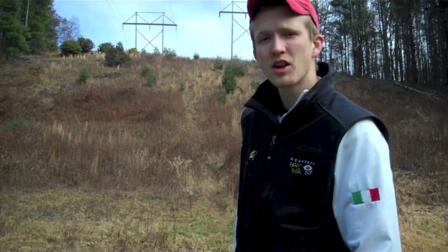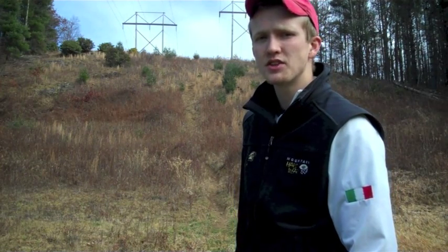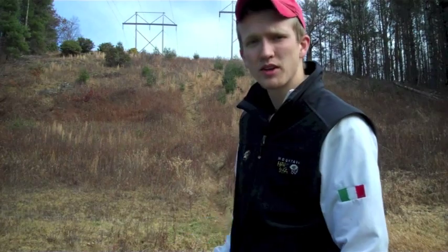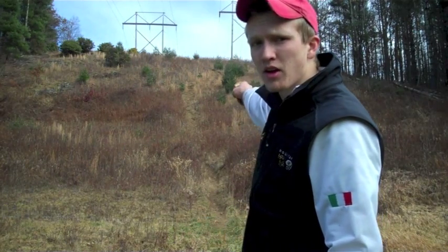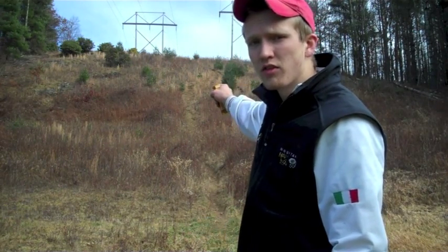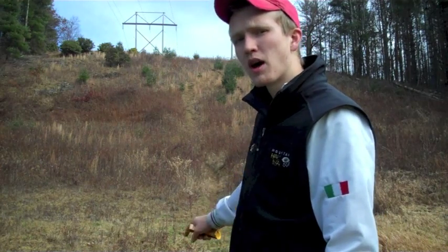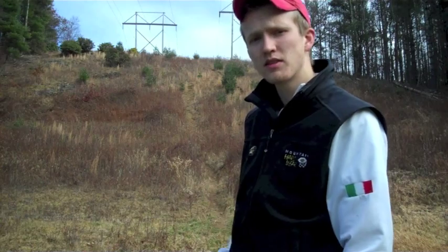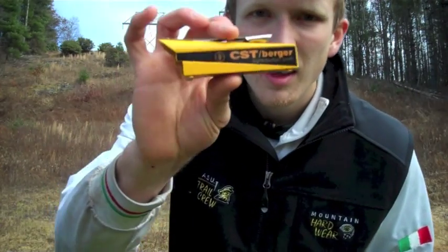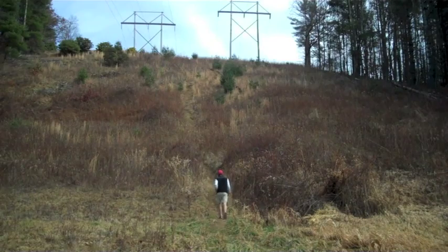In this demonstration, I'll be showing you how to calculate the elevation drop, or in other words, head, taken from the top of where your proposed siting for the intake is, down to the bottom where your powerhouse or turbine is located. We'll be doing this by using a site level.